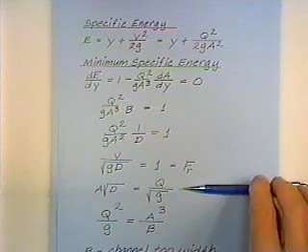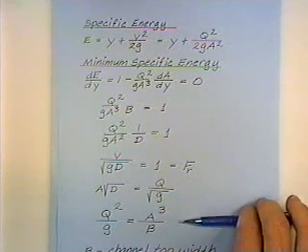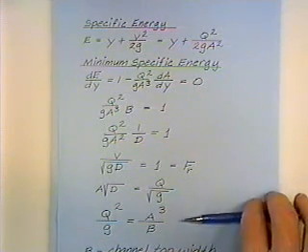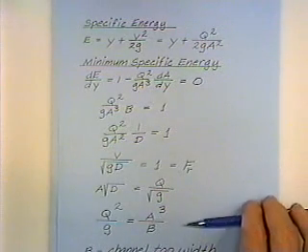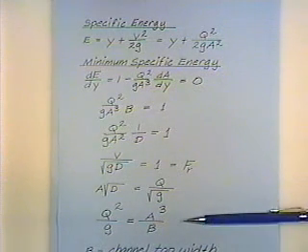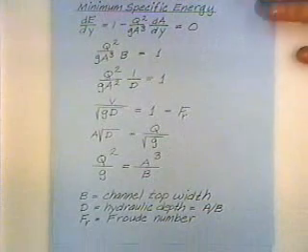The Civil Engineering Reference Manual that you have, as I recall, uses this form, which is common in many references. All these steps are just mathematical manipulations, and this is an equation that's useful for solving problems: Q squared over the acceleration of gravity is equal to the area cubed divided by the top width. The different terms are defined at the bottom there.